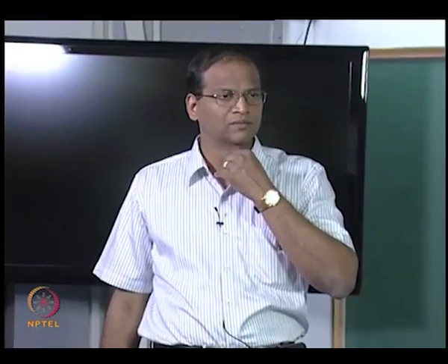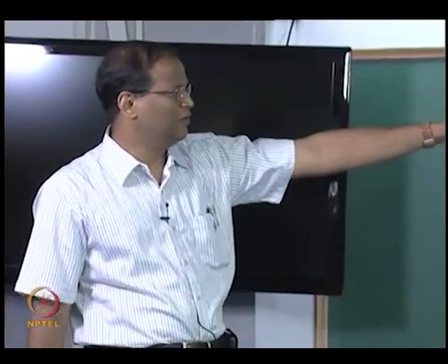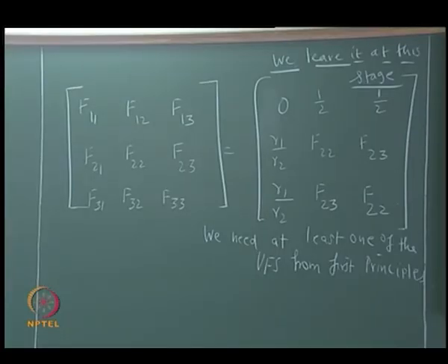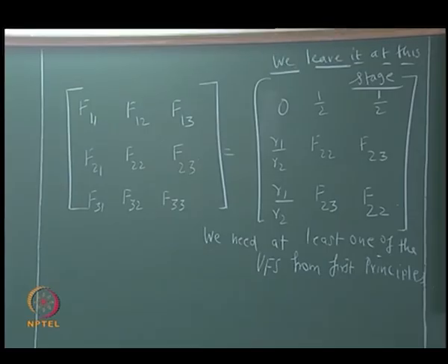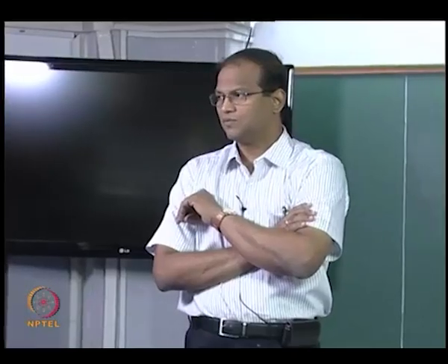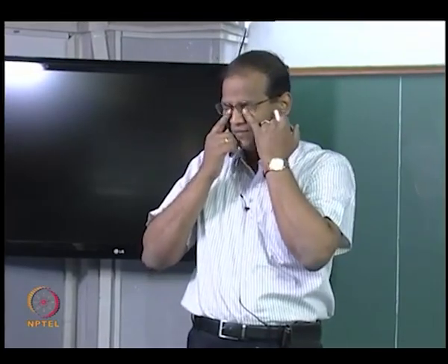You are not understanding me. If you get one of the view factors, it is done, you can't solve beyond that. The two sum rules are the same. Even otherwise, there will be one which will trouble you. You try. We have just two equations and two variables, but both equations are parallel, so we cannot solve it.